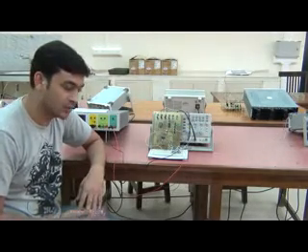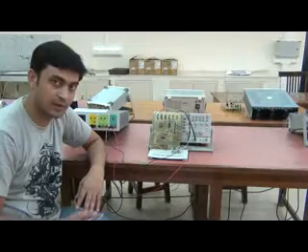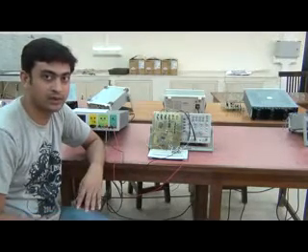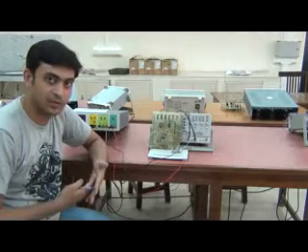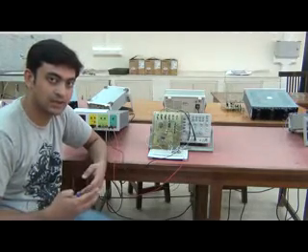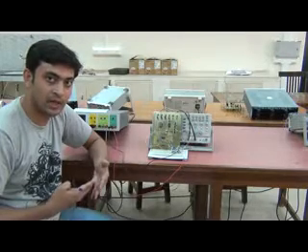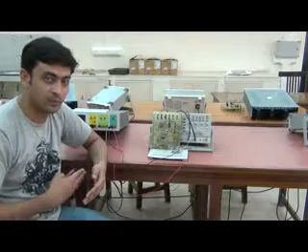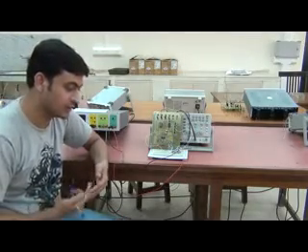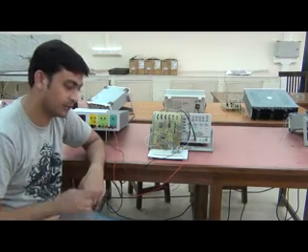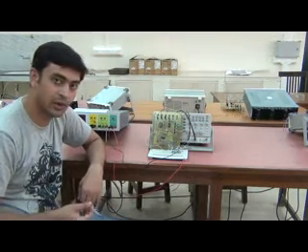The inputs given to all the flip-flops, J and K, are 1, and as explained, the first LSB flip-flop will have the clock from the digital test board, and the next flip-flop will have the clock from the complement output of the previous flip-flop. Hence we have designed this divide by 8 ripple up counter on this